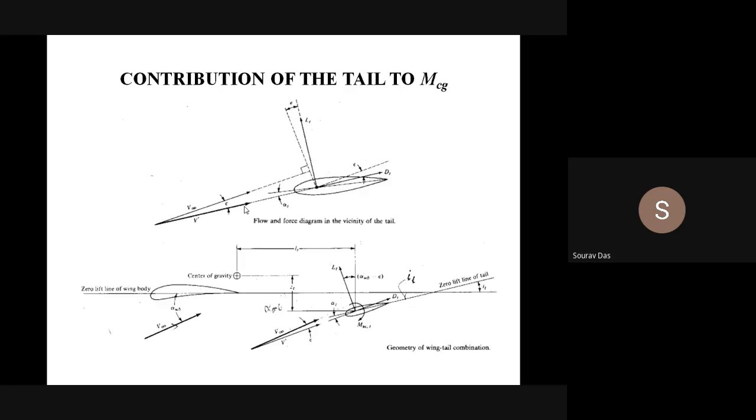So that obviously causes the lift and drag force to be deviated by the same angle, isn't it? Because the lift and drag are perpendicular and parallel to the free-stream velocity. If that is deviated by epsilon, these will also be deviated by the value of epsilon, isn't it?